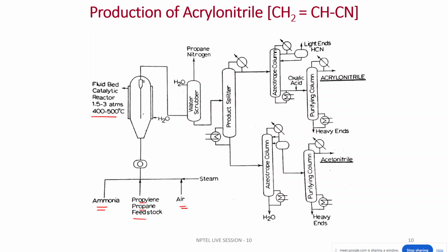As we already discussed, this is a very highly exothermic reaction. So we need to make sure that proper water cooling is being done to maintain the temperature inside the reactor. Now, to perform this reaction, we need a catalyst, and the catalyst used for this reaction is molybdenum, bismuth.